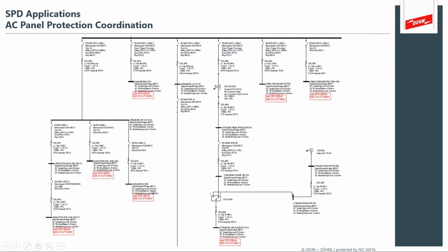And this is often associated with things like transfer switches where you have a backup generator. And you want to make sure that your surge protection devices are as close as possible to the victim equipment. And this is what we mean by coordination. You have an upstream device, you have some distance between the upstream and then the downstream surge protection devices. The standards do a really good job describing the distance to pay attention to. It's generally anything over 10 meters. We'll pay more attention to that in some upcoming slides.